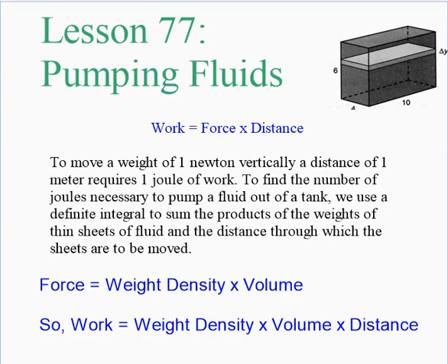In physics, we know that work is force times distance, and what we're going to do is look at these individual sheets of liquid that we want to pump out. It's obviously going to be easier to pump liquids out of the top because it doesn't have to move as far as it would from the bottom. To move a weight of 1 Newton vertically a distance of 1 meter requires 1 joule of work. And so that gives us a definition for work.